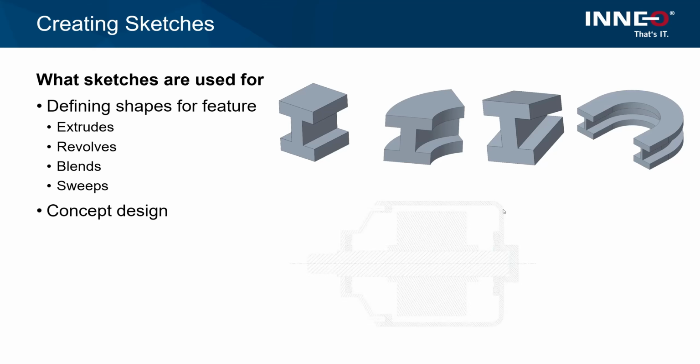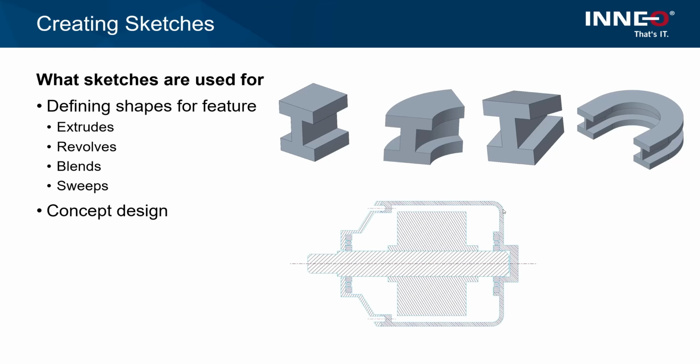Sketches can also be used for conceptual designs. If you want to create something in 3D but you just want to work on an idea first, you don't have to go and model all the parts. You can start with a simple sketch in 2D and create all the entities to check how they will actually fit together. Is the design going to work in the space you've got? And then from that point onwards you can go and use the sketch information, that same sketch, to create 3D geometry as well.